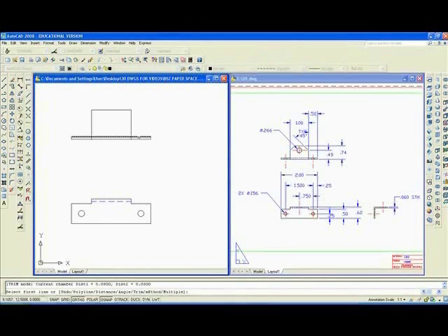And D, enter, which would be 74 minus 49, which would be 0.25. So for D I'll put 0.25, and the second chamfer distance is 0.25, so I'll simply pick the two lines, enter, pick these two lines.